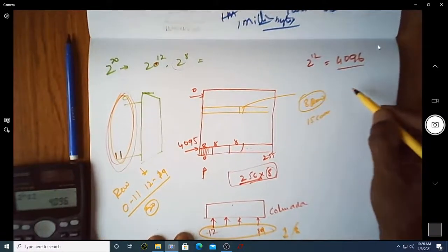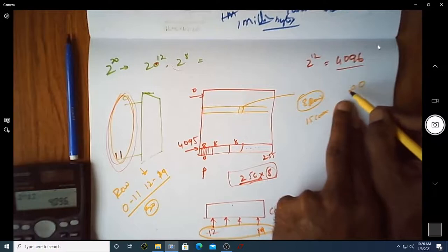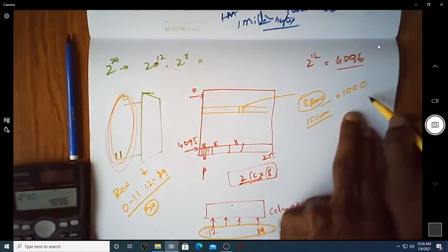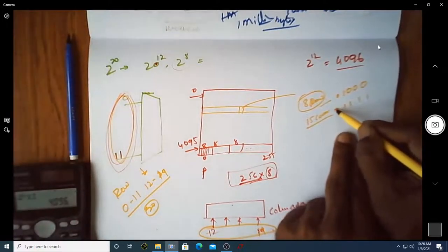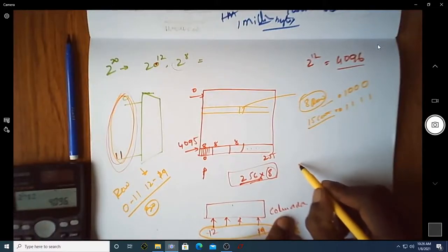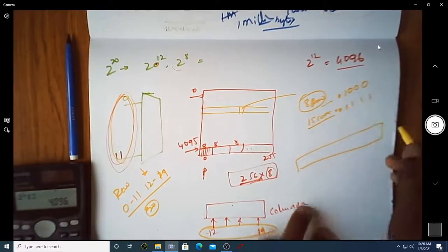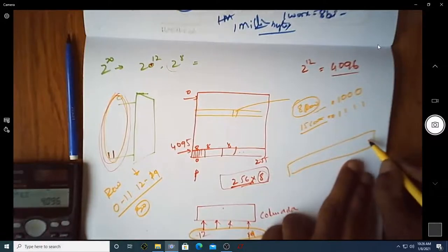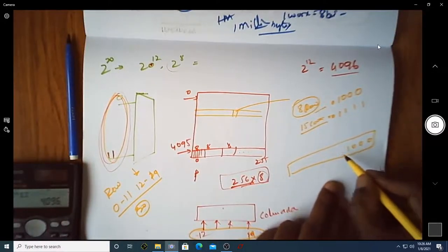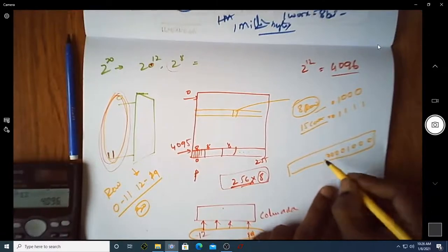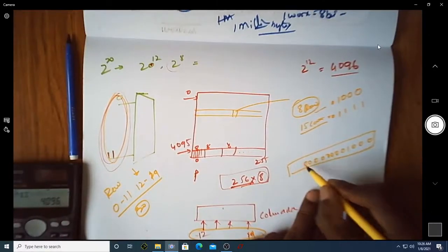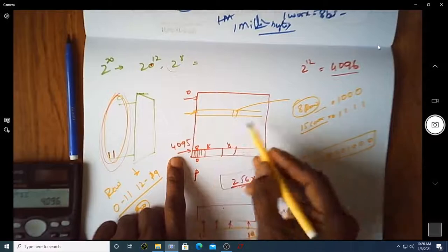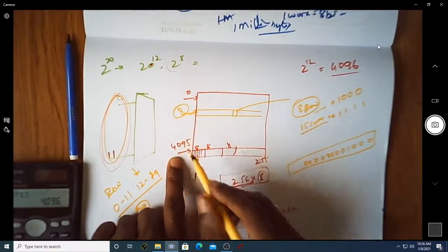If you are looking for the 8th row, you can think of having the address as 001000. Out of 20 bits, the first 12 bits happen to be for the row, so you can think of having 0001, and then 0000. So this is now 8, this is now 12. This is the address for this particular row, which is in the 8th position.